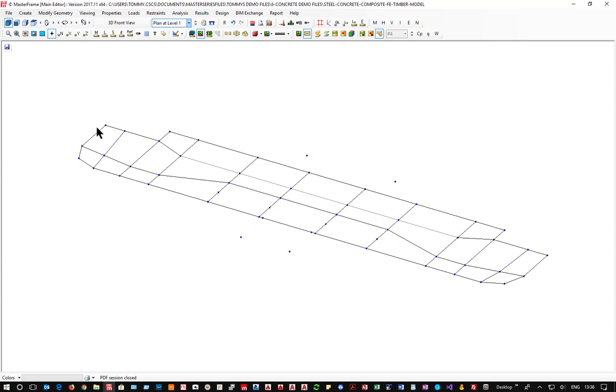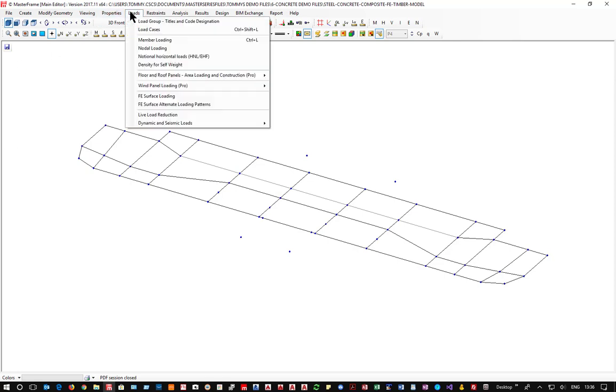And I've got all these intermediate internal members. Now, if I was doing a flat slab and not wanting to do pattern loading, then I wouldn't need to have any of these internal members, just the column node points interfacing. But the reason I want to do pattern loading is because if we look, not at the surface definition, but